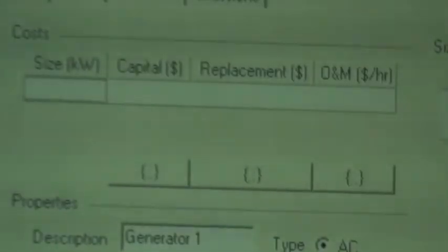But remember, if the genset is not enough, HOMER will tell you that the genset you suggested for dimensioning the site is not enough, so increase the size of the genset. If you want to do trial and error, you can actually go for 4 kVA, which is literally not available, and see whether HOMER can cope with 4 kVA or not.